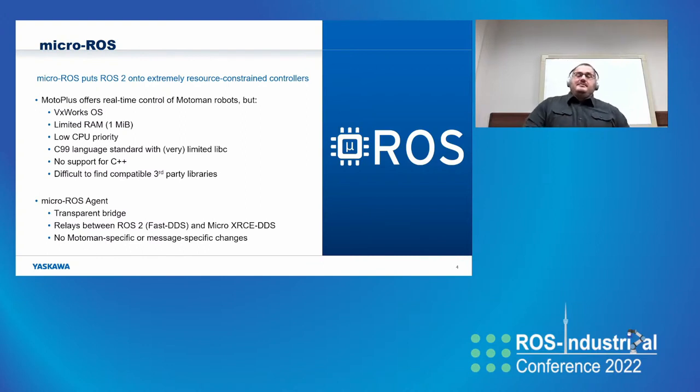There is an element that runs on the PC. It's a bridge, if you will. The beauty of it is that there's no customization specifically for the Motoman. We didn't change anything. We didn't edit anything. If we add a new message, it doesn't matter. It just automatically takes care of all that for us. So MotoROS was a good solution for adapting the code to run in the MotoPlus environment so that we can control the robot in real time directly on the controller.